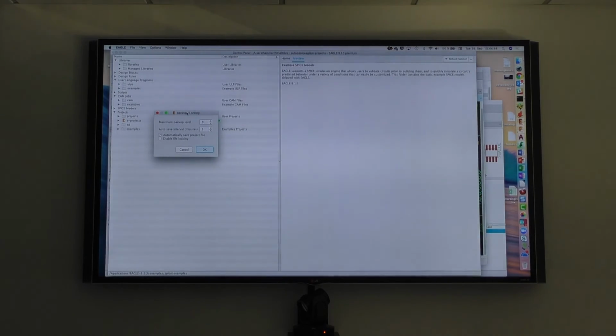Okay, but we have backup files. You don't see it in Eagle, but you take Windows Explorer, your Finder, whatever you have as the file manager, go into the folder, look at what the latest backup is, save it with a new name with the correct extension, and then load it again, and then it works again. So you have lost maybe, ideally, 5 minutes, or a bit more, depending on what happened. But we have backup files.